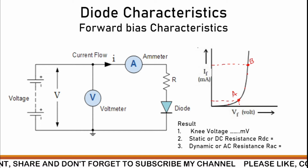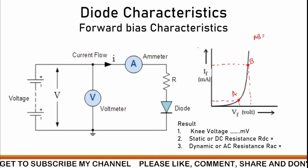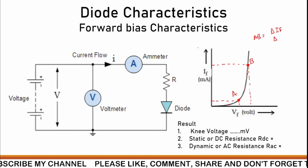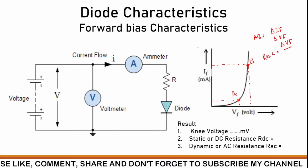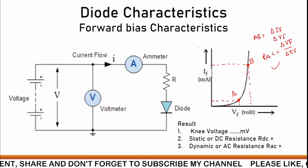So we have AB, where we have delta IF and also delta VF. The calculation of RAC is very simple: delta VF upon delta IF. The result is a resistance called the AC resistance, which is also called the dynamic resistance.